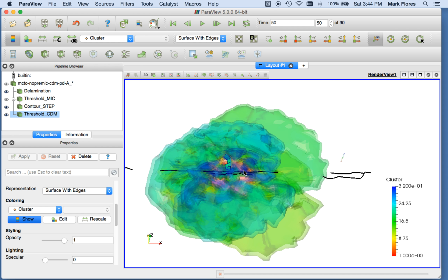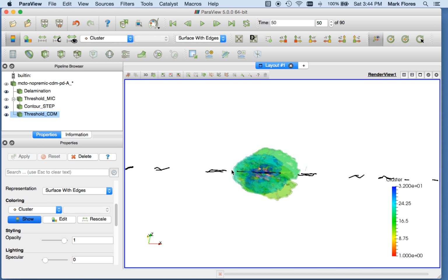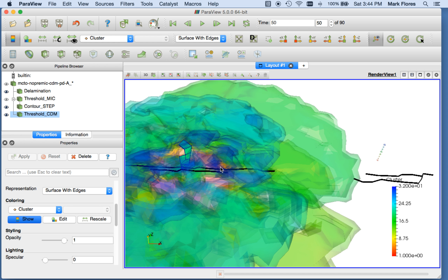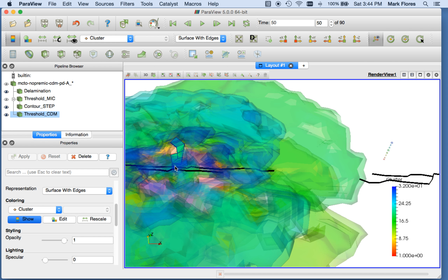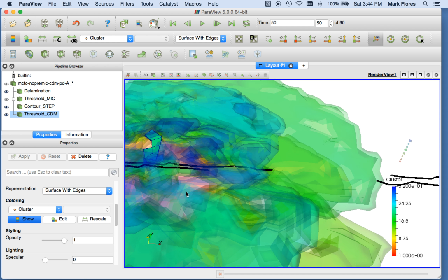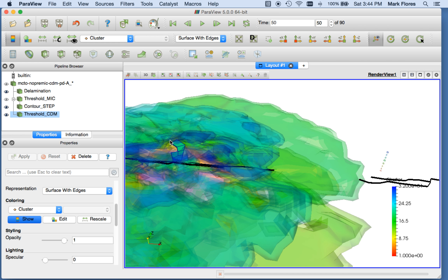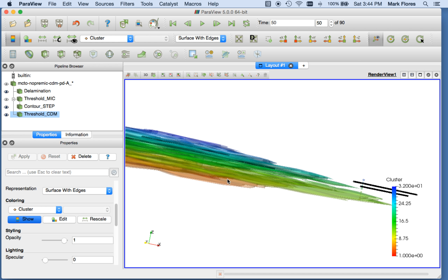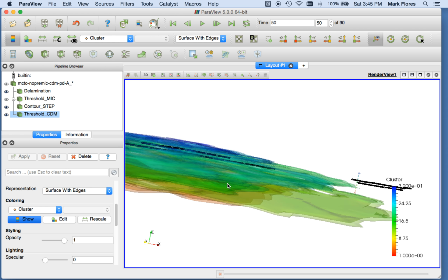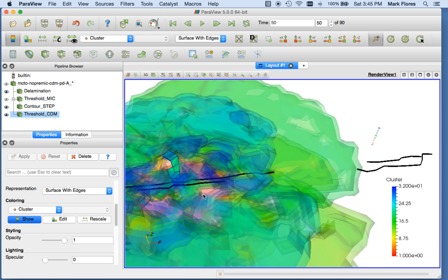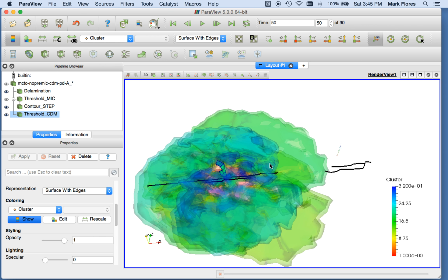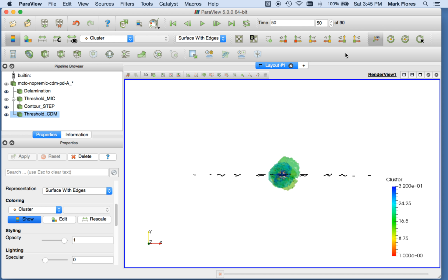And if you were to actually rotate some of this, the fiber damage occurs on the 0 degree ply. So you can see how fiber damage occurs in relation to transverse matrix cracks. And of course, there's also a morphology to this. Because it was impacted, there is morphology to this. It's kind of hard to see when you have so much damage, but that's how it looks.